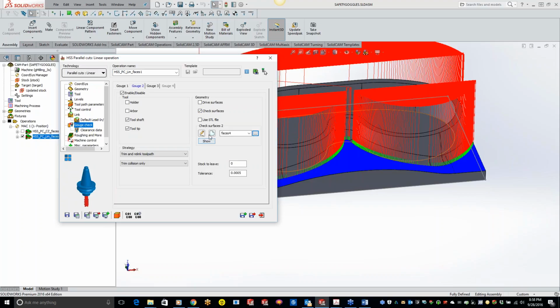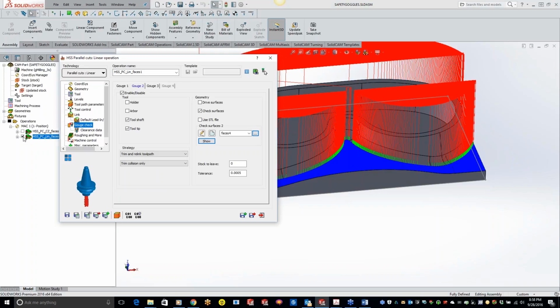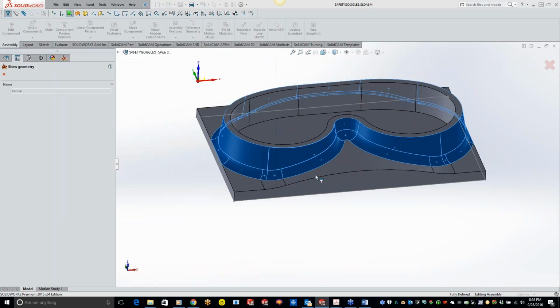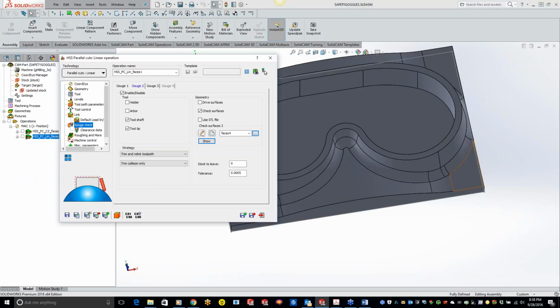If I do a show right here, I'm telling it not to touch those surfaces, but if I had my Kurt vise in here or whatever vise, I would do a check surface against that too, or maybe it's even a toe clamp that's sitting over here. It will definitely completely avoid that every way possible. So it will definitely go against anything. Thank you, Cody. It's good having you.